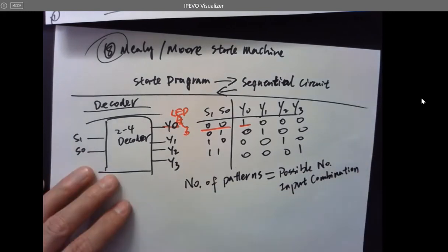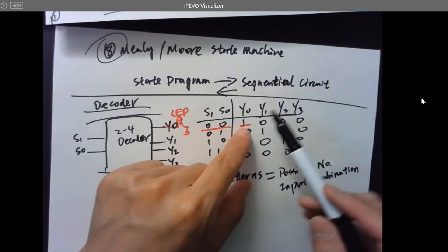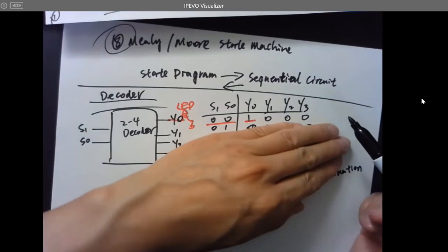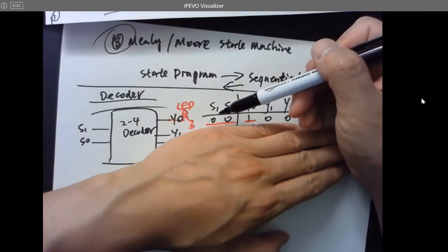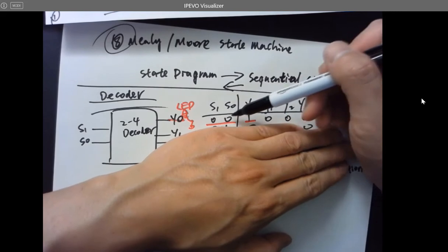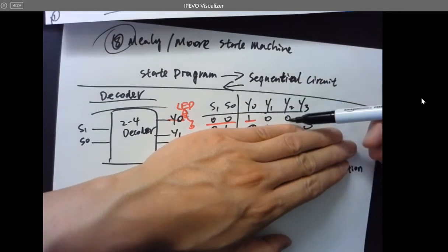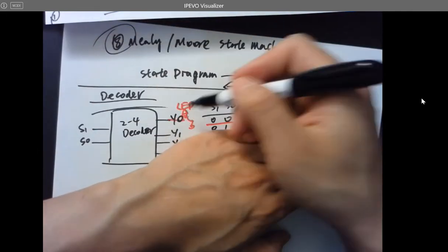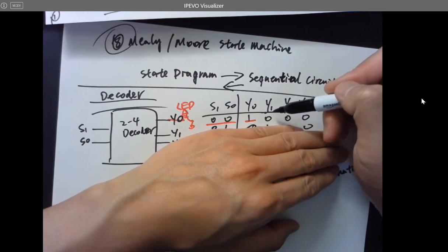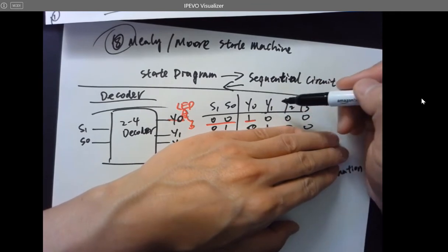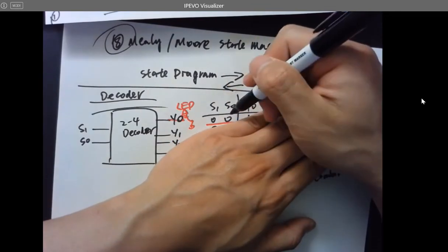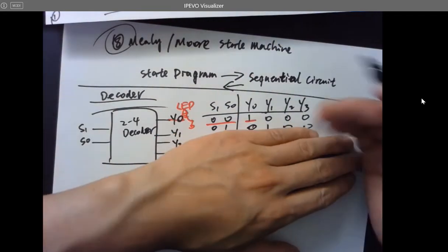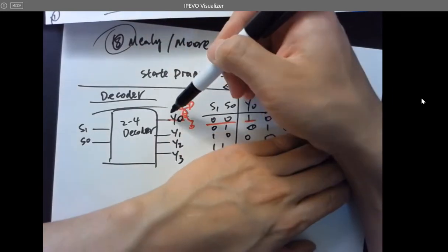Think about if this is right, okay? So this is one output pattern, right? Let's look at y0 is 1, y1 is 0, y2 is 0, y3 is 0. So this is one output pattern, and you need one input. It's like a password. It's like a code, right? You need this code to represent this pattern. So whenever the system receives that code, it's going to output this pattern. It has to be 1 to 1. You cannot have one type of input give different types of output. It doesn't make sense. The decoder, right? You have a code, it's decoded, and you get a pattern of output.